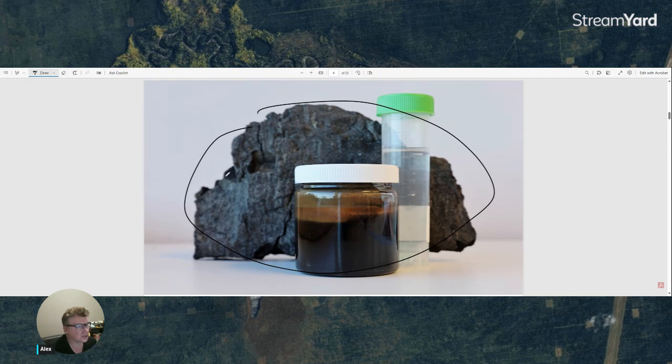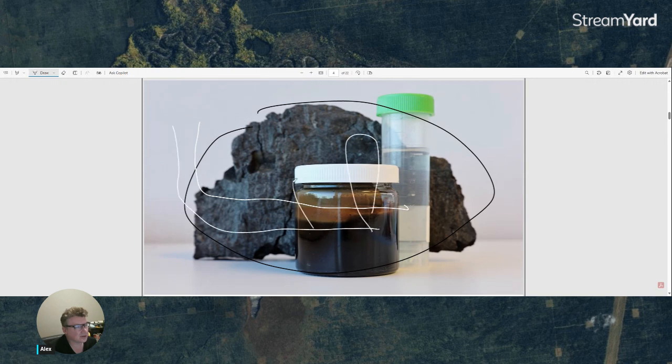If we just look at the rock at the back, you can envision the well pairs that we talked about: injector, producer, and then chamber development to drain that oil by gravity, if that rock was 40 meters in height. And then the liquid that drains possibly looks like this, where you have oil and water, or maybe some kind of foamy oil because of NCG co-injection.